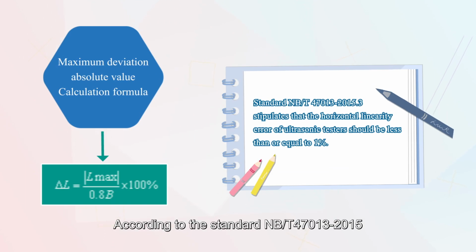According to the standard NB/T 47013-2015, the horizontal nonlinearity error of the ultrasonic detector shall be less than or equal to 1%.